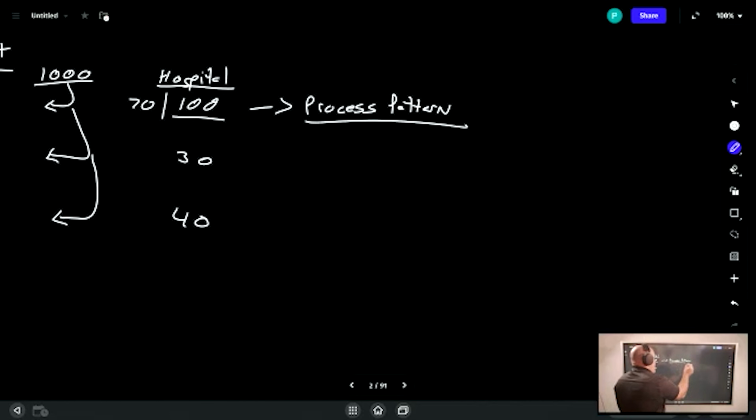And what does that look like? The process pattern is where we're going to say, okay, we're 30 hours over. Why are we 30 hours over? We're going to do some root cause analysis. And like I said, we determined our subcontractors weren't properly lined out. They weren't properly trained on how to install things, and we had to go and fix stuff. Okay, so we start to develop a subcontractor lineout process.